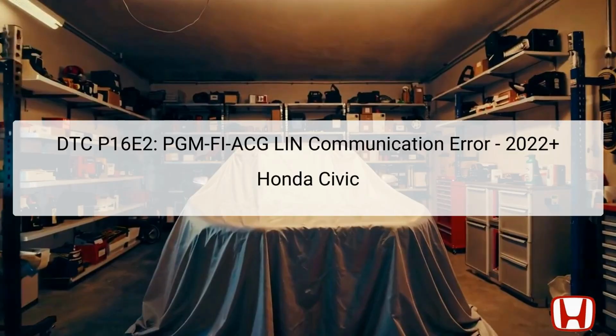The DTC P16E2, or PGM-FI-ACG LIN communication error, specifically relates to the communication malfunction between the Powertrain Control Module, PCM, and the alternator via the Local Interconnect Network, LIN. This error indicates that the PCM is unable to receive critical signals from the alternator, leading it to conclude that an abnormality exists in the system.